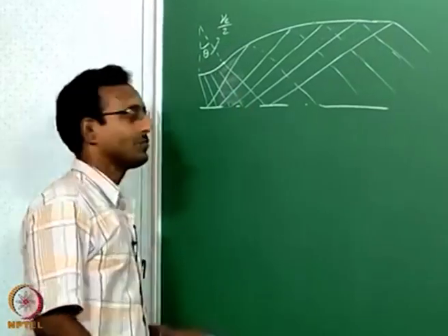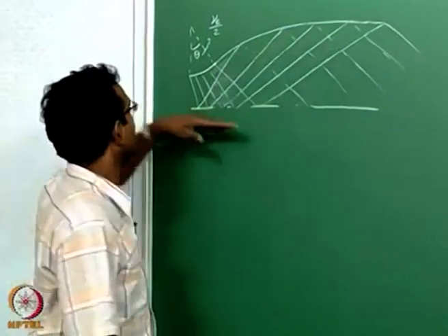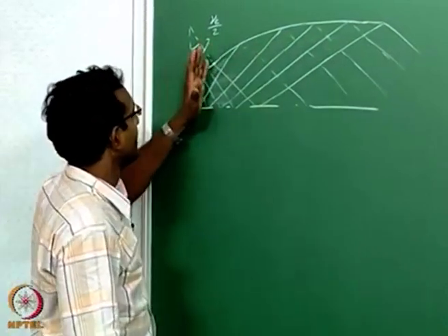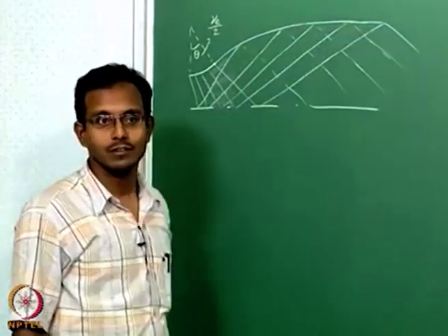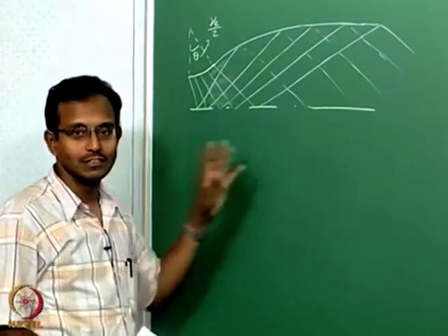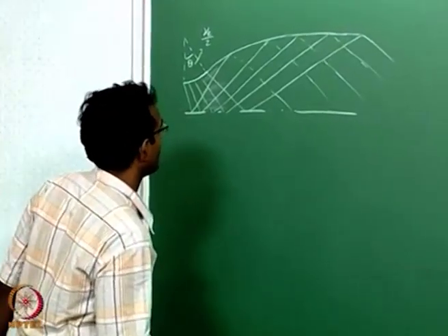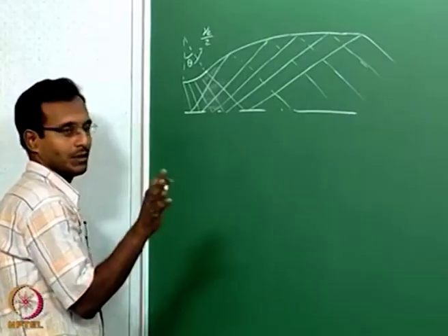That is the idea of this other part of the compression, smooth compression wall. Initially we have a smooth expansion wall and then a smooth compression wall. This is the whole sequence of how we will have a nozzle downstream section designed, okay, the diverging portion of a CD nozzle designed. Upstream portion, of course, we won't worry about too much.